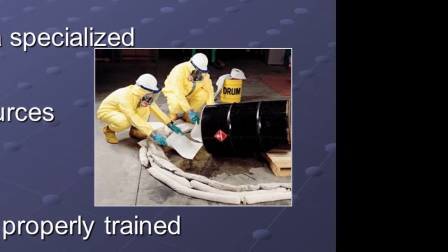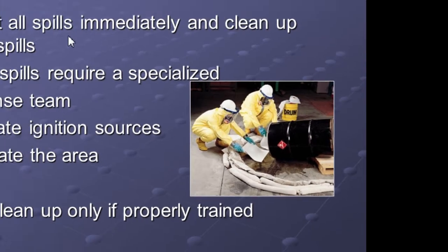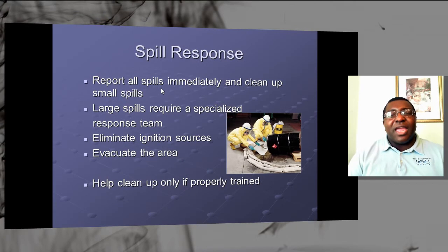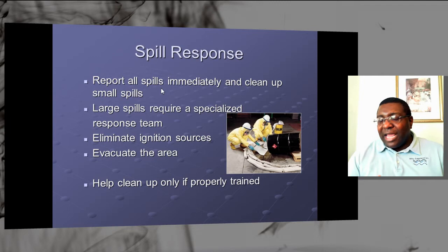If there's a spill and you can't isolate it, it keeps moving and moving, and that spill gets larger and larger, and then it becomes even harder to deal with. So you want to grab that spill as quickly as you can, isolate it, contain it, and then absorb it, whatever that chemical is, with some absorbent pad.